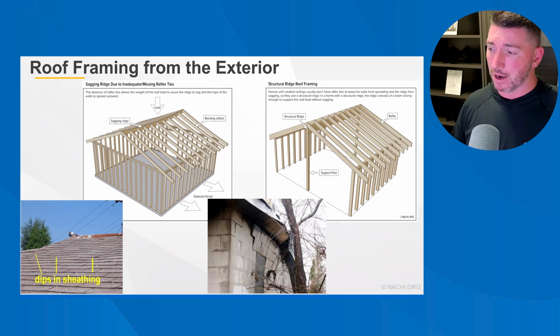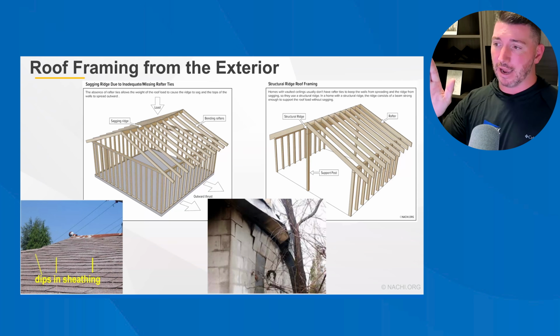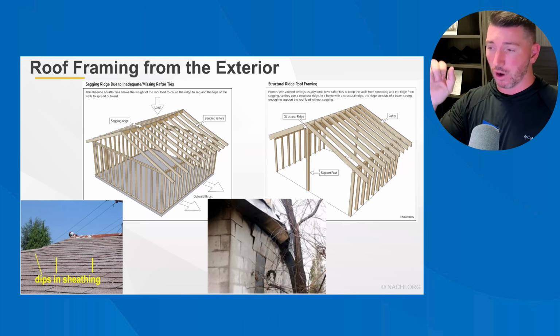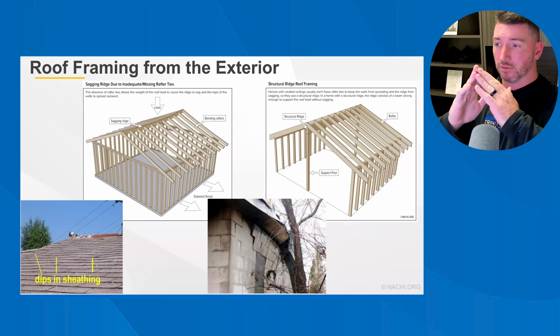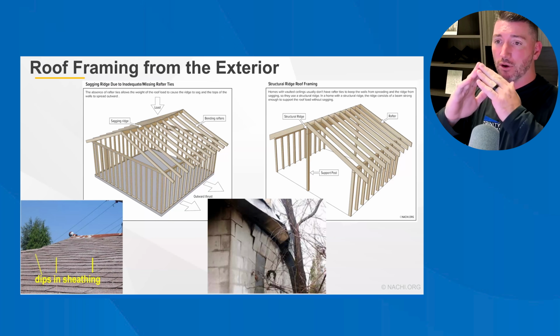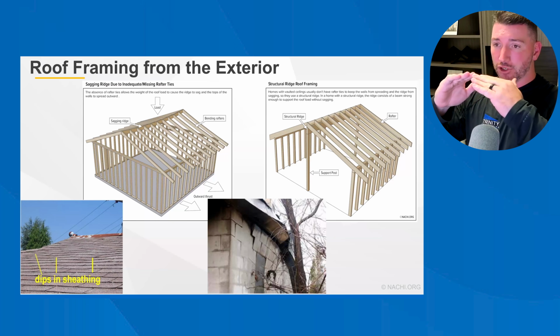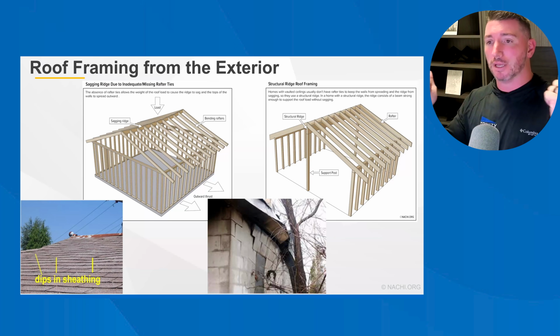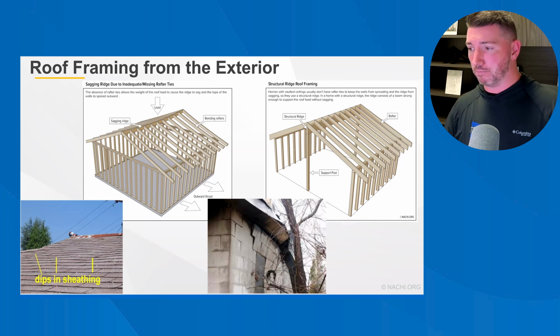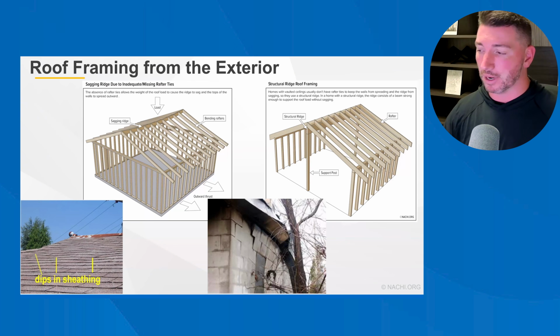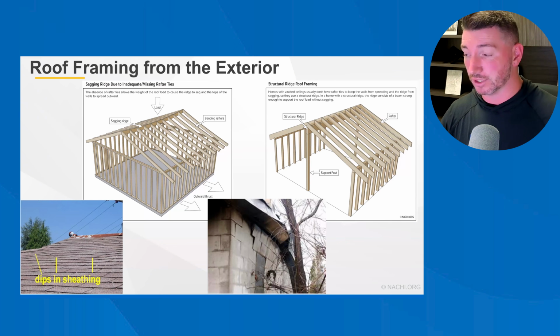And then that middle bottom is a cinder block building, concrete structure. And when that load comes down, that gravity load causes that ridge beam to sag. Well, they're rigid framing members, right? So if you've got a sag in a triangle in the middle, it's going to push the triangle out on either side. And so that's where you've got the bending rafters causing outward thrust on that wall, and it's compromised the integrity of that structure to a significant degree.